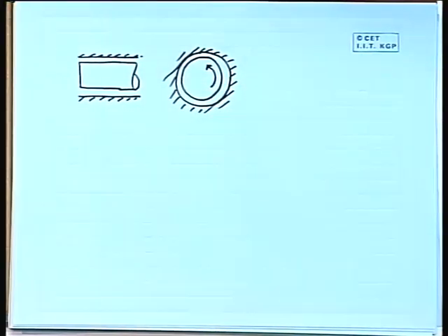Here also, if we know the RPM of the shaft and the gap, then we can calculate what amount of force is required to overcome the resistance. Now, where is that effort going? It is dissipated in overcoming the viscous resistance. The mechanical energy we are supplying cannot be destroyed, so it is transformed into another form of energy which is not recoverable, thermal energy.